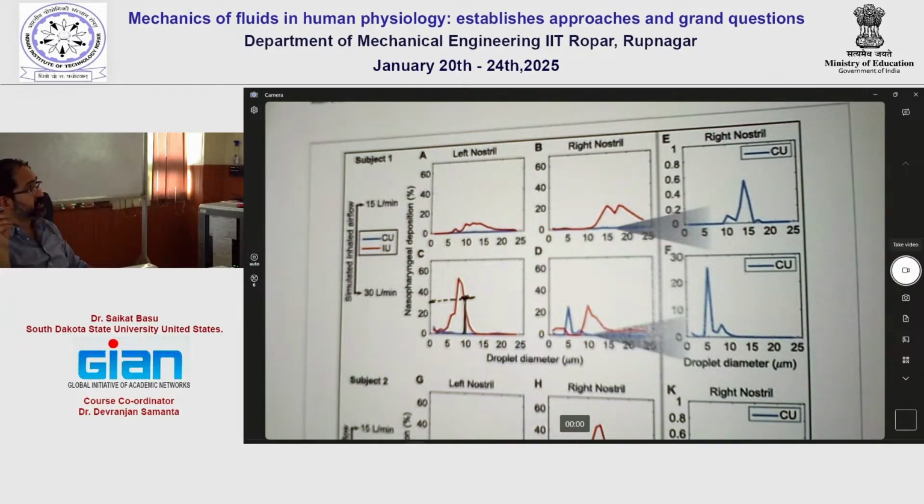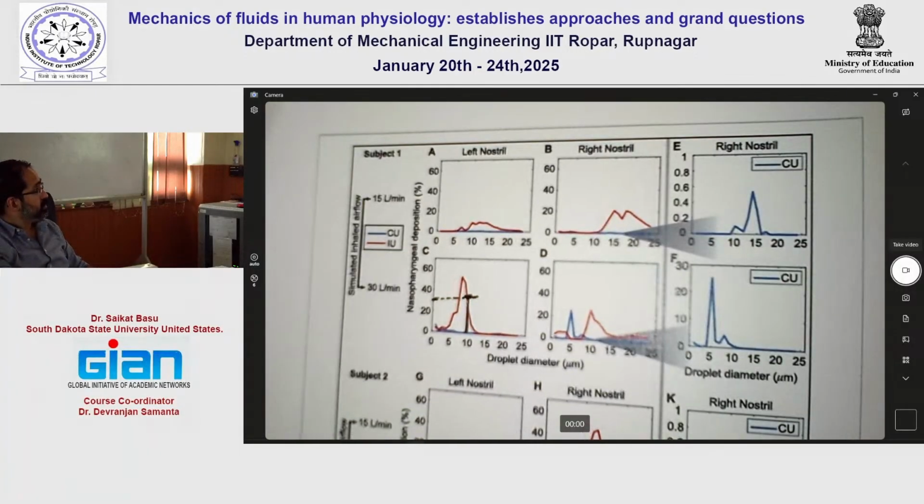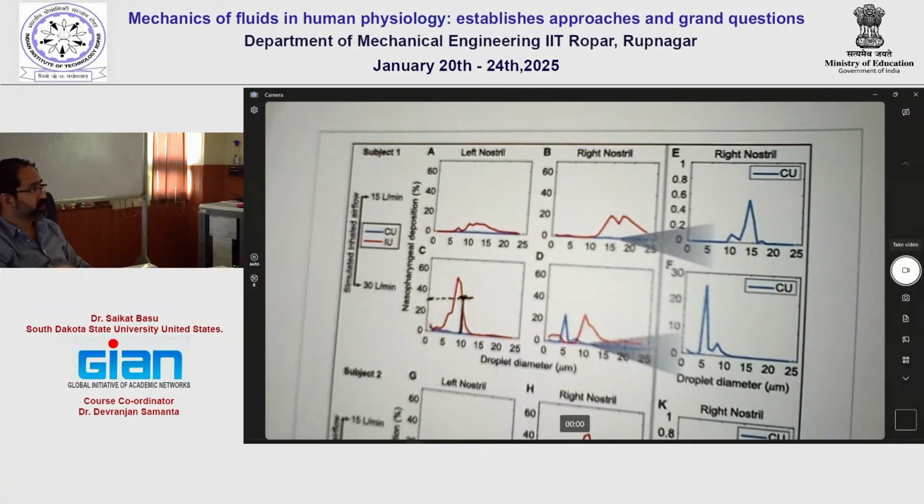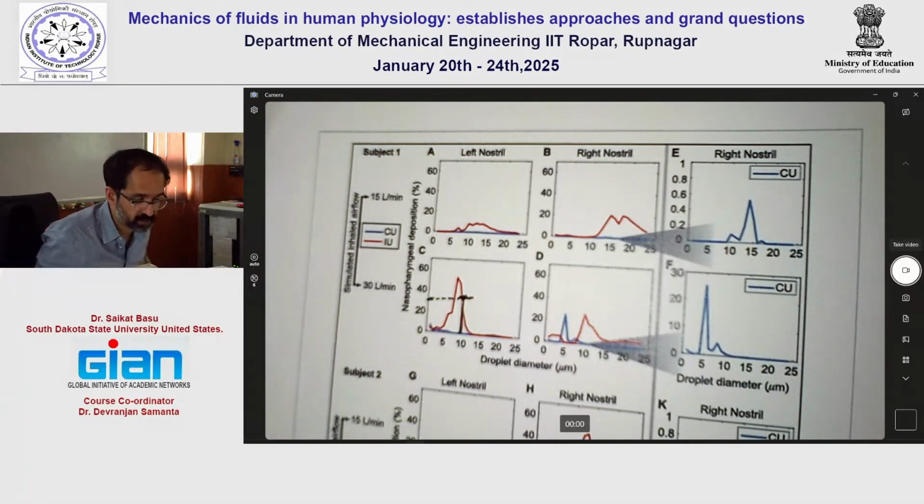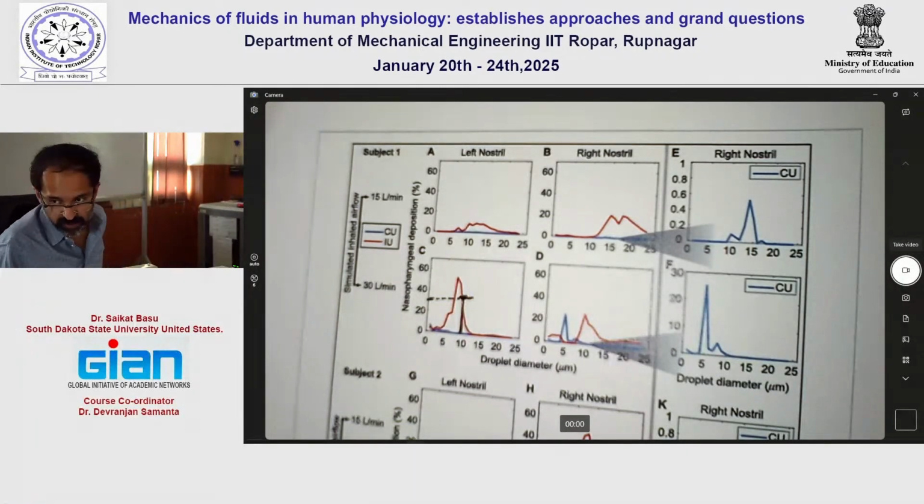34%. So you can see the number. You can do it more accurately than what I did here. But that is basically around the same number, right? Although I did use a new flow simulation, because the moment I change the mesh a little bit, as we run a new flow simulation, things change. The flow rate is not precisely the one that was used in that particular paper, but you still get the same order of magnitude, basically the same value.